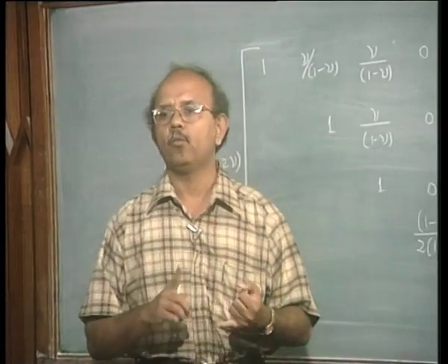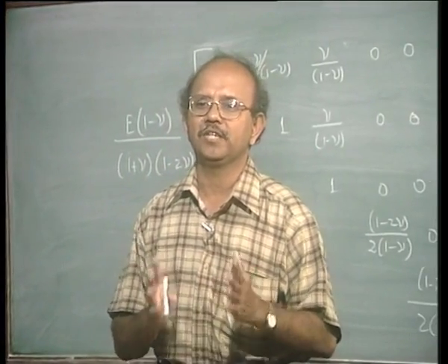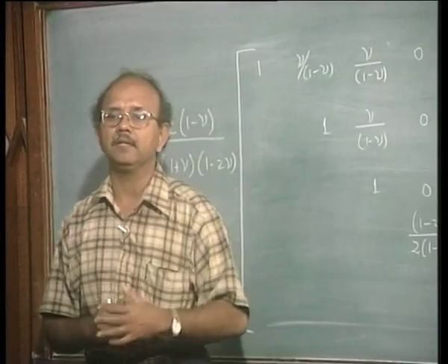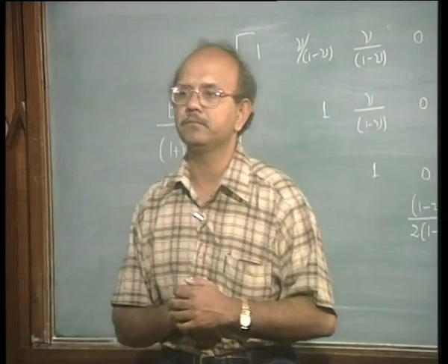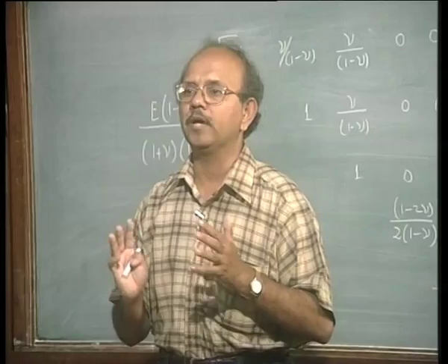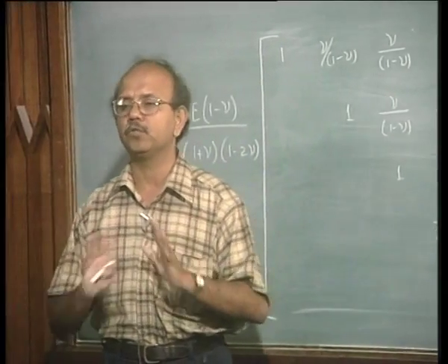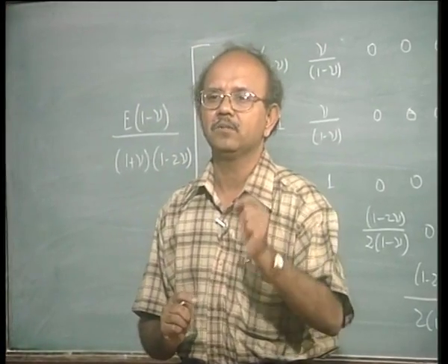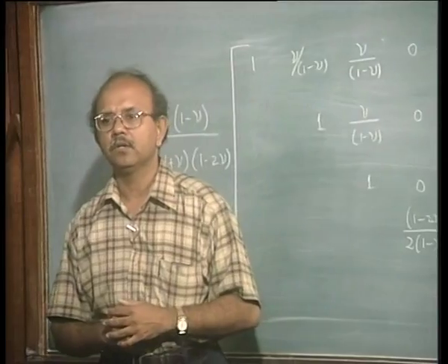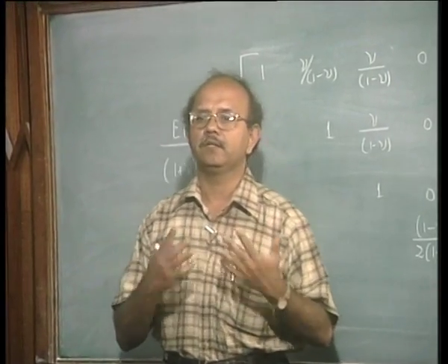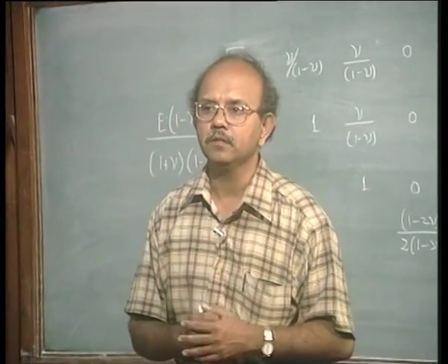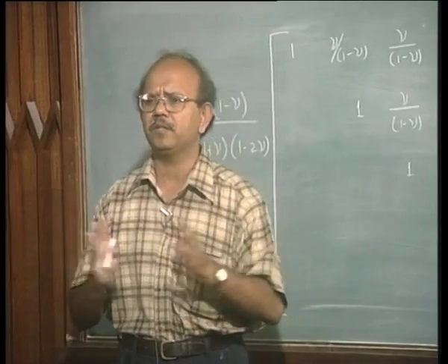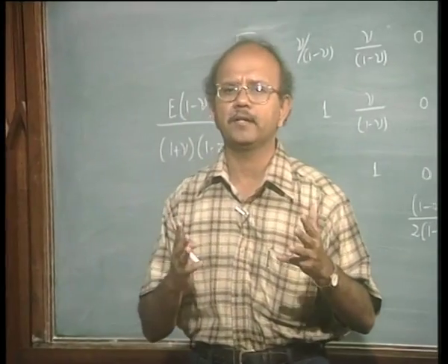So there are two things to this issue. One is that it is much easier to generate a mesh, or in other words define a mesh, very accurately and very easily with respect to a 2D geometry. 3D mesh generation is still difficult. In most cases, in fact 100% of the cases, you will be stuck with elements called tetrahedron elements, which do not have certain good properties. We are going to see all that later in the course. So we can generate nice elements using the 2D case. And the results, when your assumptions are right, will not be any different or will be very slightly removed from the results that you would get with the 3D element.